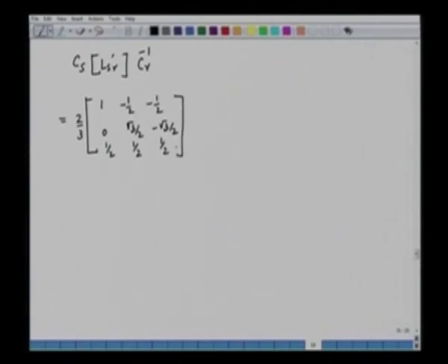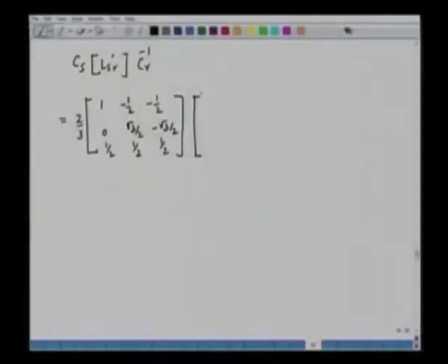Now, what is LSR? LSR is the mutual inductance between the stator and the rotor. Now, this inductance is a function of theta r. So, if we see this inductance we have derived in the last lecture, this inductance was a function of theta r in the following fashion.